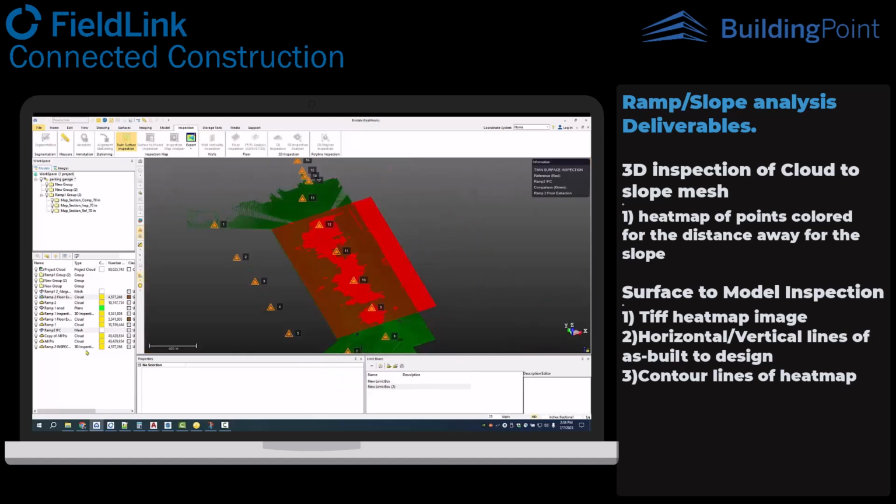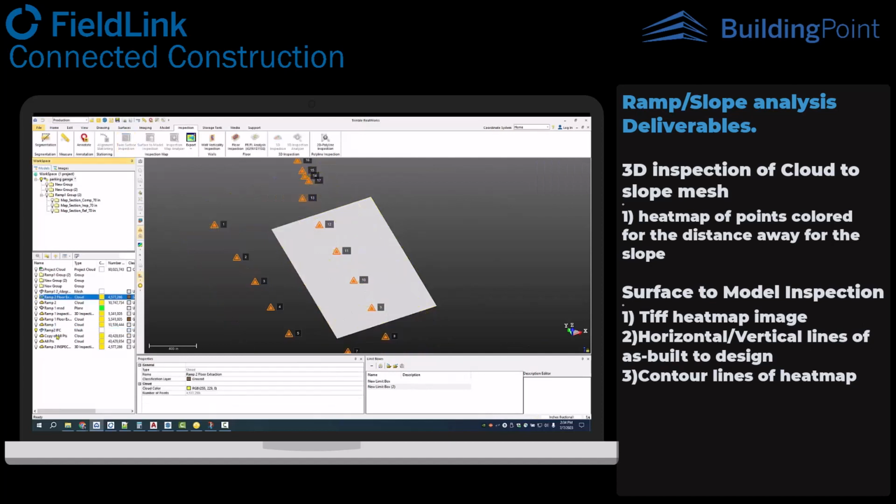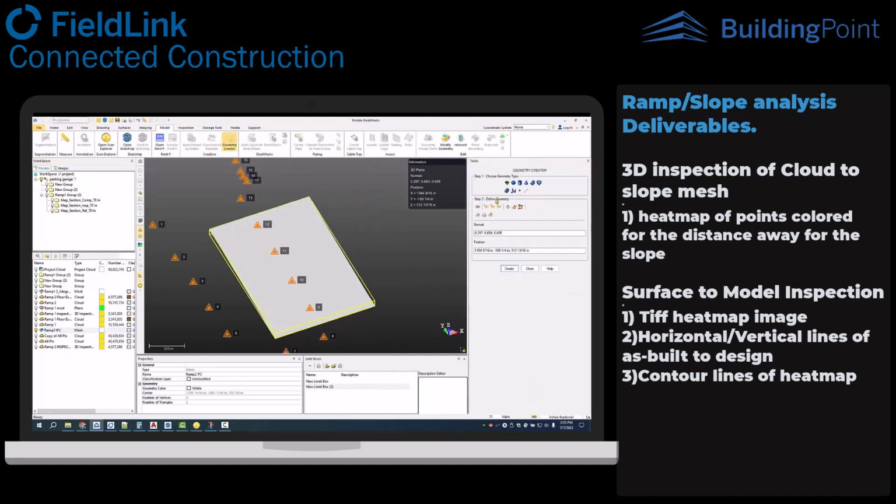What I actually will do instead is turn off this other one, and instead of going from the point cloud to create this, I'll do a geometry creator from the IFC I imported, just because I feel like that's a little bit better rather than going to the point. It's just going to fit this to the plane. Let me try that one more time.